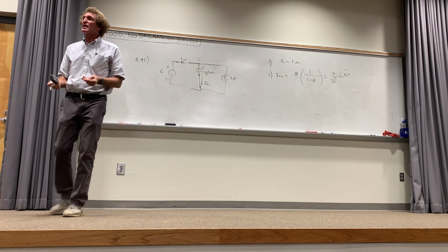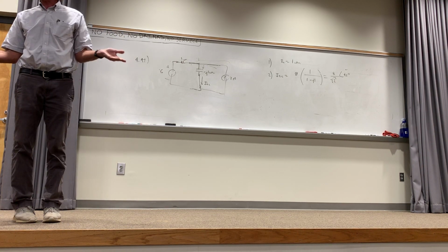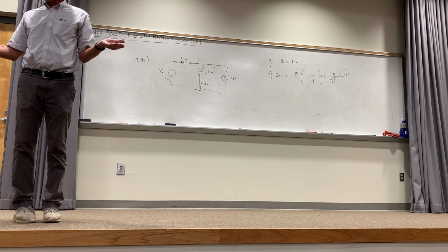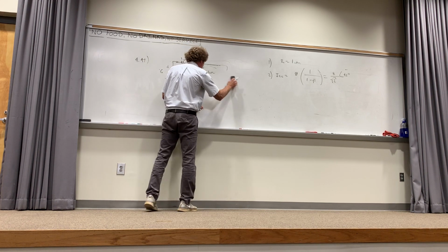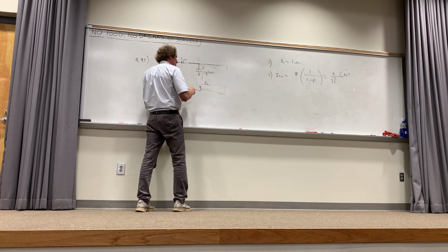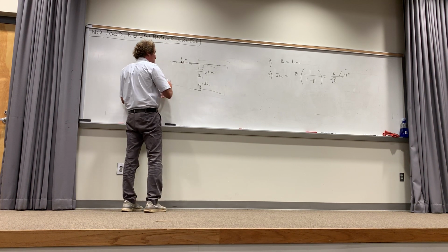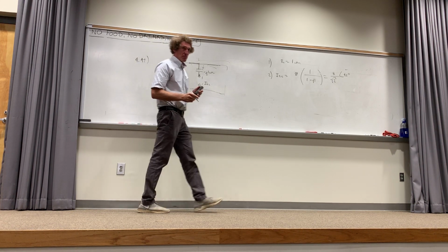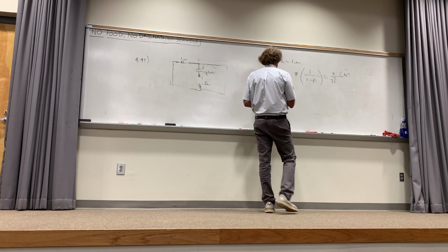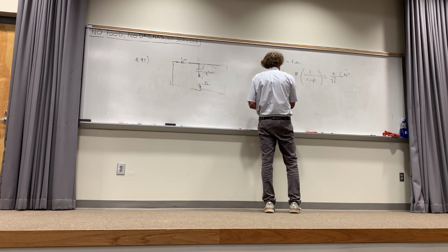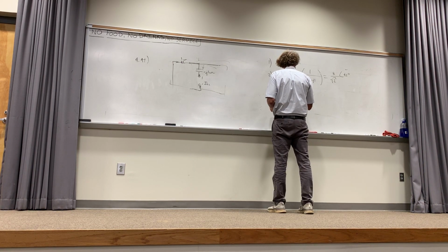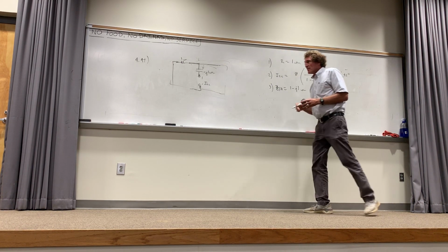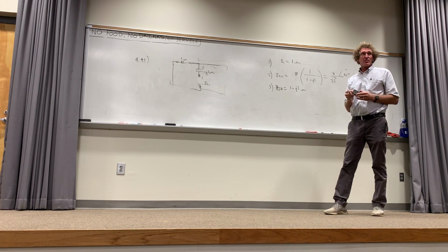You notice that R Thevenin is going to be the same whether it's a Norton or Thevenin problem, right? Always the same. We know what R Thevenin is. That goes away. I'm looking for the Thevenin equivalent resistance between these 2 points. That becomes a short circuit, and it's simply 1 minus J1 as before. So the third thing is our Z Thevenin. I call it R Thevenin. Z Thevenin is just 1 minus J1 ohms. Everybody see that, class? It's the same as before.